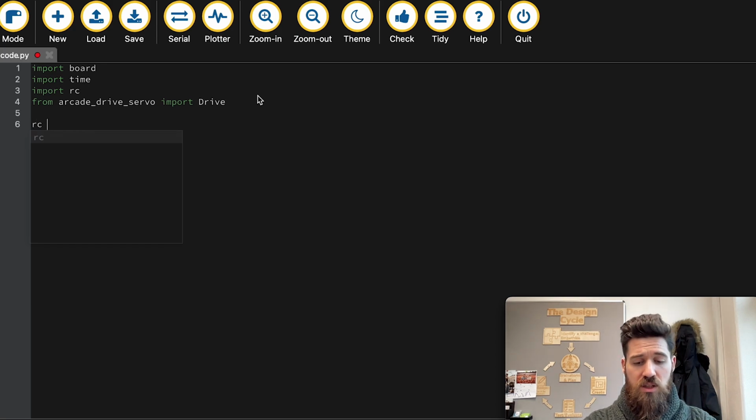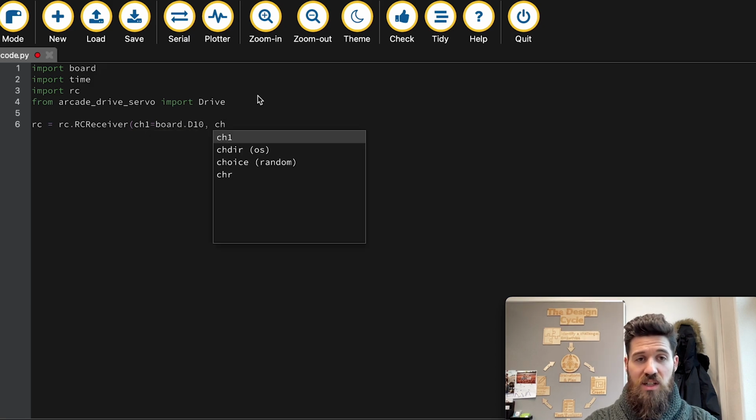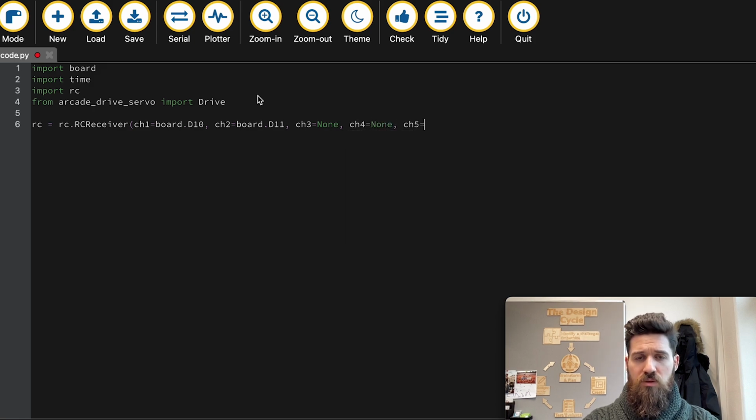So just like in last video, we're going to initialize our RC object. And we're going to say channel 1 is equal to, in my case, board D10, same thing as last time. Channel 2 is equal to board.D11. Channel 3 is equal to none. Channel 4 is also equal to none. Channel 5 is equal to board.D12. And then channel 6 is equal to board.D13.